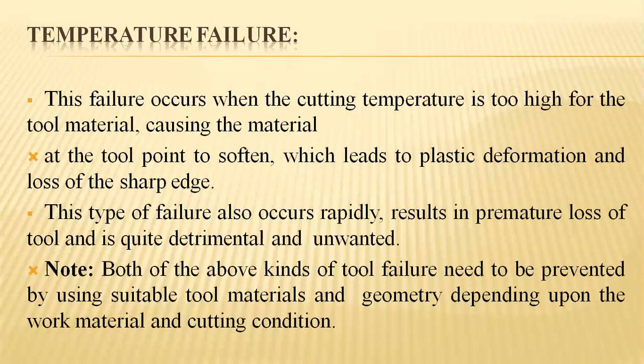And this causes the tool point to soften, which leads to a plastic deformation that completely changes its dimensions beyond the recrystallization level, and the sharp edges will be getting lost. And even this failure occurs rapidly, which results in a loss of tool.